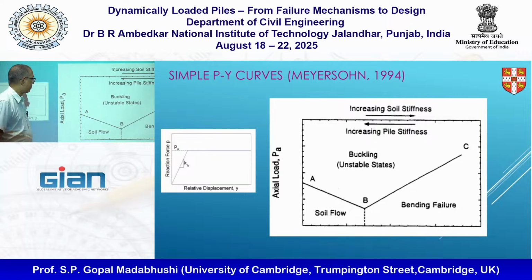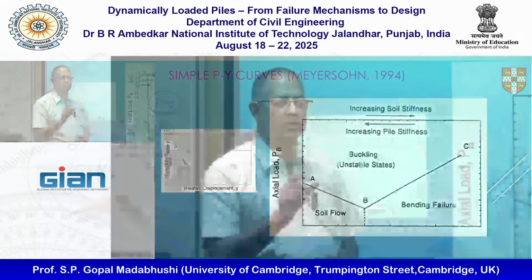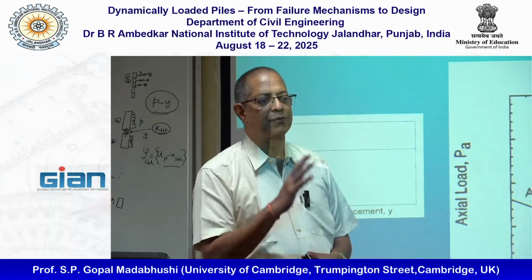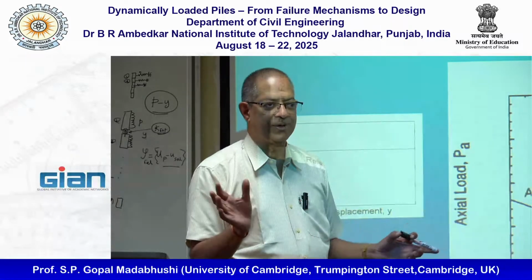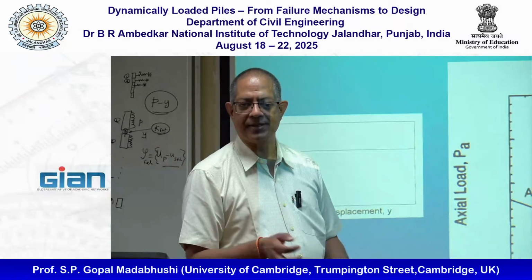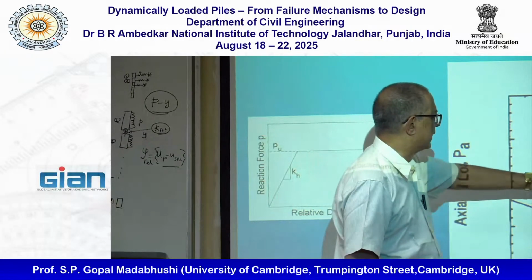And how big this is depends on, of course, the pile stiffness, but also the end conditions. Is it a free-headed pile or fixed-headed, pinned, whatever the structural joint is, that will determine the magnitude, but certainly it will be in this space.